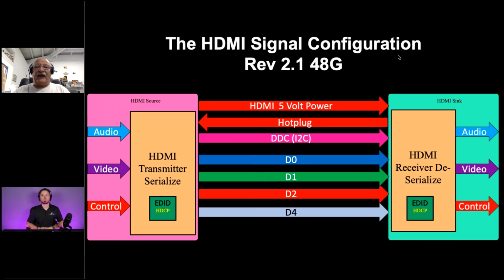So the transmission line has a lot to cover, and they're not exactly linear as per frequency response. If you ever looked at an insertion loss curve, which you do, you've got the equipment to do that, it's pretty obvious. You see these things start rolling off. But then there's a little thing in there called Nyquist, and Nyquist in many cases helps us, and in some cases hurts us. Again, that's another discussion, another day.